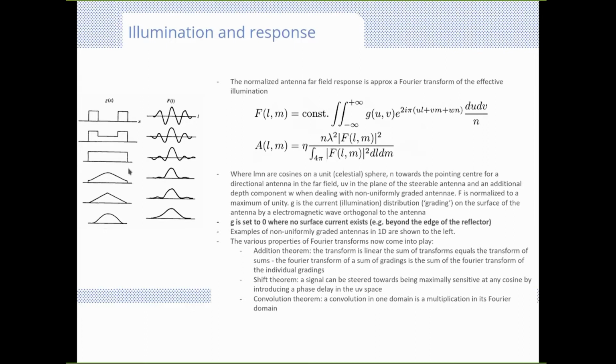But in all cases, there is a Fourier relationship between what we measure. So a box-like thing will look like a sinc function. If you look from the top down onto a MeerKAT dish, it will roughly look almost like a box. So it will have something looking like a sinc response, right? That's the voltage response. If we square that, we get its power response, and that's what we indicate here by the A of l and m, right?